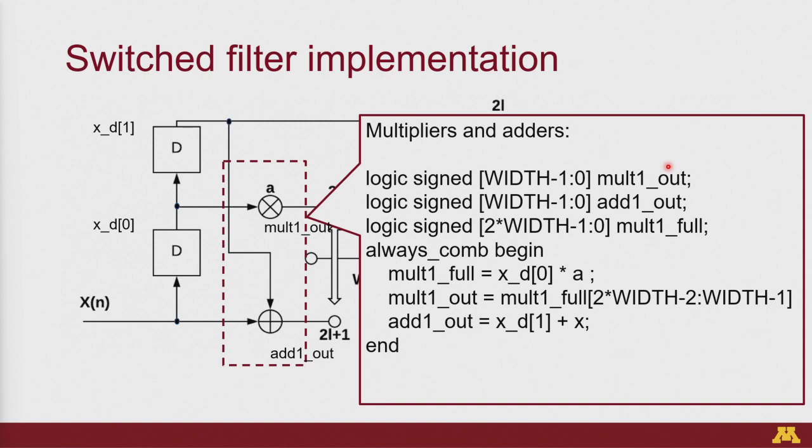Now when you multiply two of these, you're going to have 16 bits in total on your output. But because you defined it as 2 bits integer and 6 bits fractional, in your new output you're going to have 4 bits integer and 12 bits fractional. Does that make sense? If you multiply two 2-bit integer numbers, you get a 4-bit integer number. But from Verilog's point of view, it does not know any of this. It just multiplied two 8-bit numbers and got a 16-bit number.